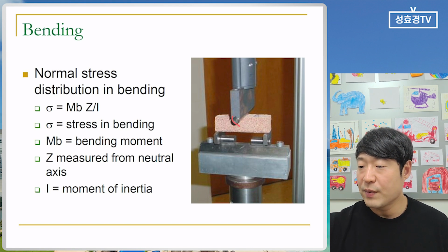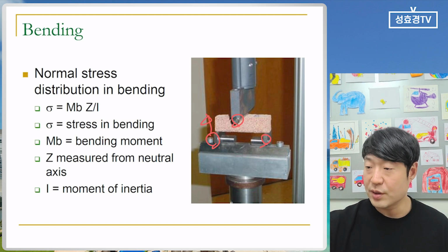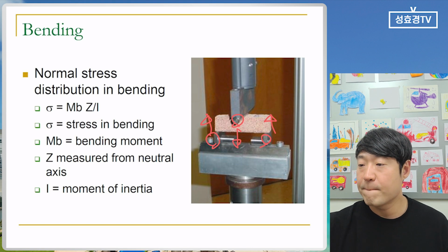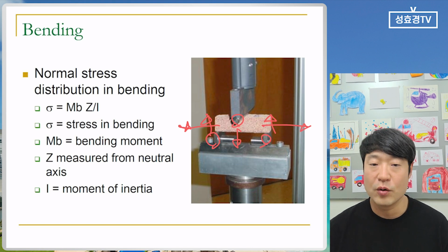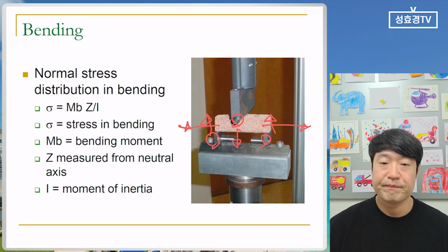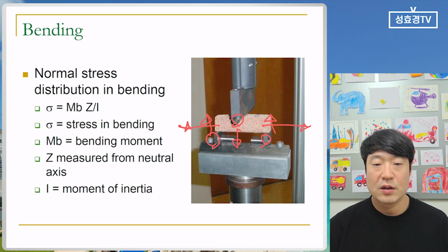Here is the 3-point bending test. Here the load direction is in this area. If there is a crack and the crack grows, it opens, so the mode is the same as opening mode 1. The bending test is good for understanding cases where there are layers in the surface area. Bending in some direction helps understand the deformation behaviors of the materials.